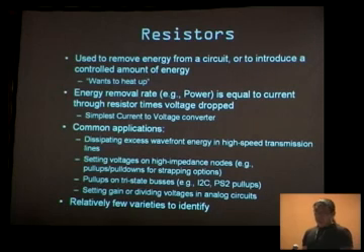They're also used for setting voltages on high impedance nodes, like pull-ups and pull-downs, strapping points. If you look at things where they want to set the frequency or the voltage of a particular chip, sometimes they'll strap them with resistors. They're used for pull-ups on tri-state buses, like the I2C and PS2 pull-ups. In analog circuits, they're typically used for setting gains or dividing voltages.